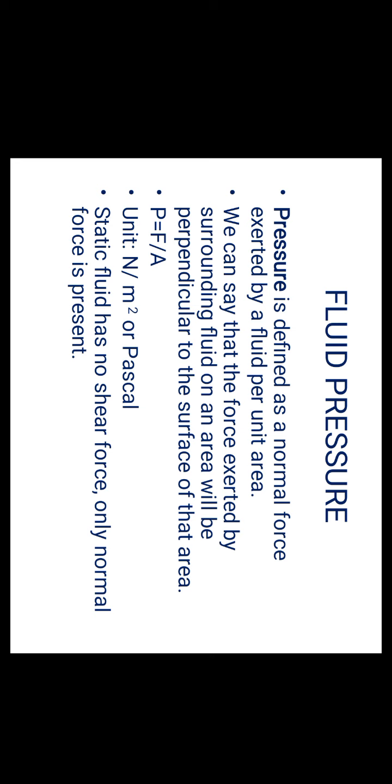So there's an equation: pressure P is equal to force F by area. Its unit is Newton per square meter, or its other name is Pascal. Then megapascal, kilopascal, depending on the values, we can give several units. And another one is bar. You have heard that atmospheric pressure is usually expressed in bars. 1 bar is equal to 10 raised to 5 Pascal, or 10 raised to 5 Newton per square meter.